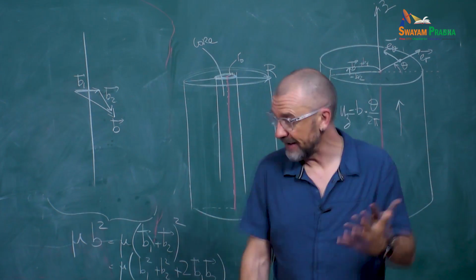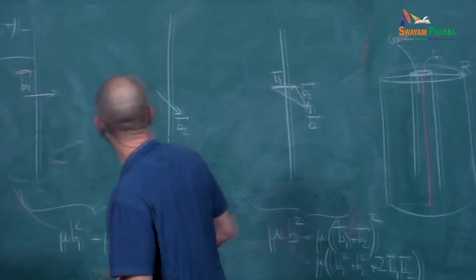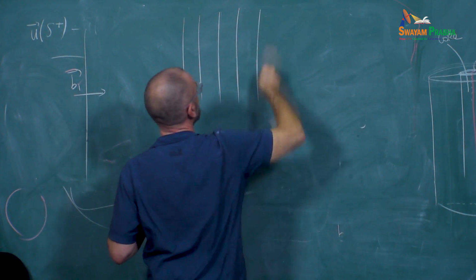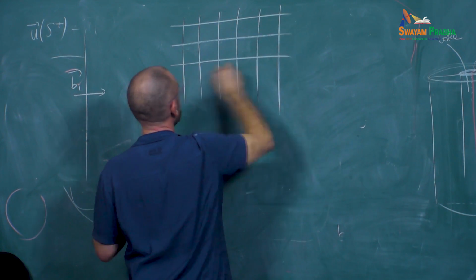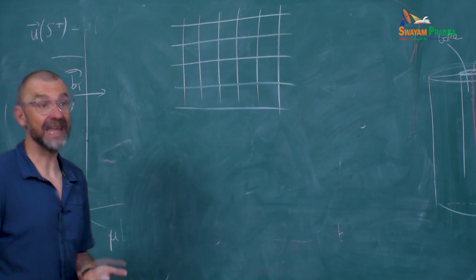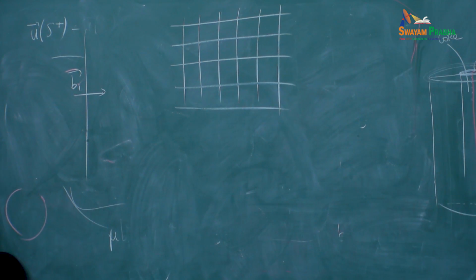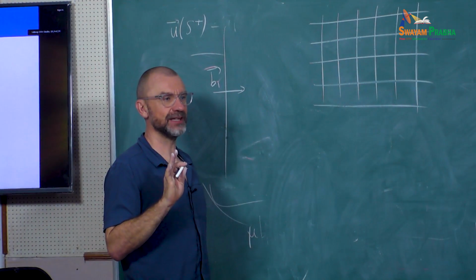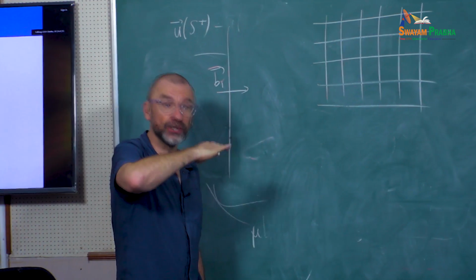So if I have a crystal and I want to create a dislocation in that crystal, let's take a good old simple cubic unrealistic crystal. And I want to create an edge dislocation. I do the simplest thing I can do. So what do I do to create an edge dislocation? With, let's say, using a shear procedure. So let's do it with shear. It's easier with shear to see what is happening. So with shear, I need to define a cut surface.